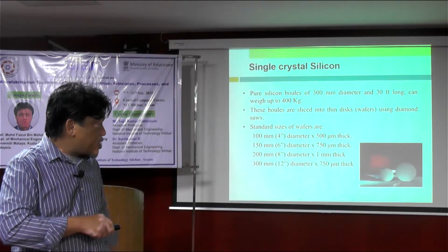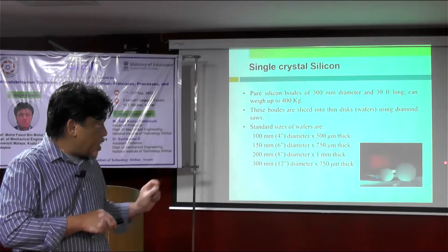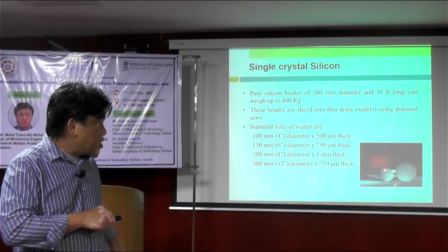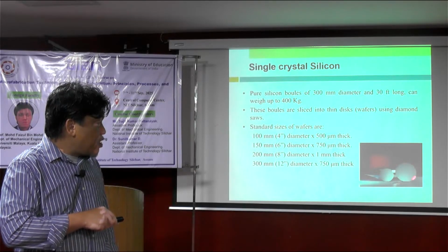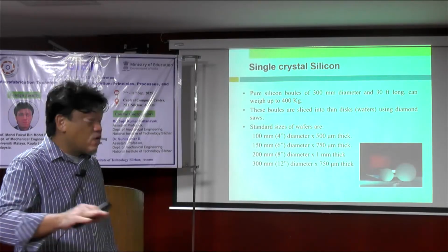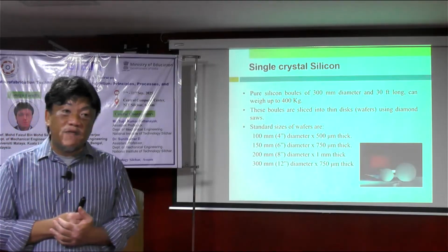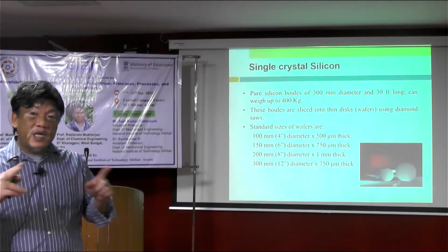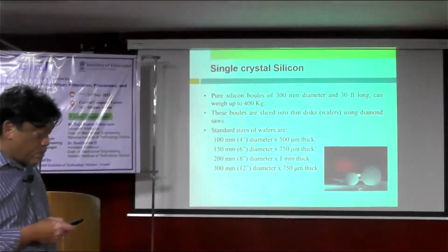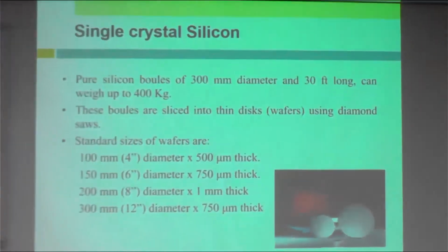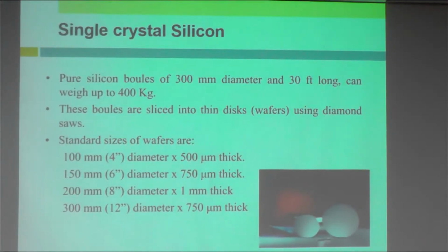Because it's batch processing, meaning you have a few chips designed, then you slice, take out the chip and package it. But in this bigger size, you can put a larger number of units in one go of the process. So that will reduce the cost basically. That is one of the reasons you want a bigger wafer dimension, to have batch processing more efficiently. Then you can reduce the production time and reduce the cost as well.